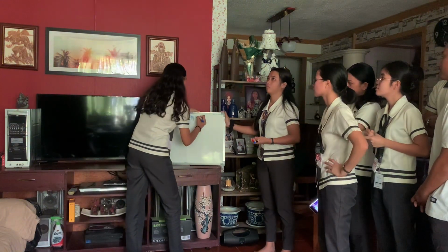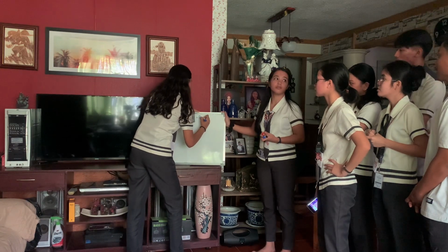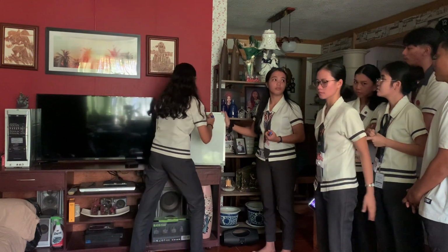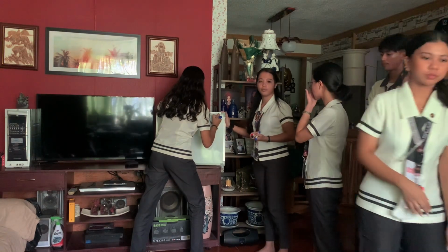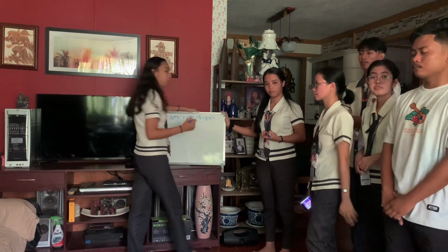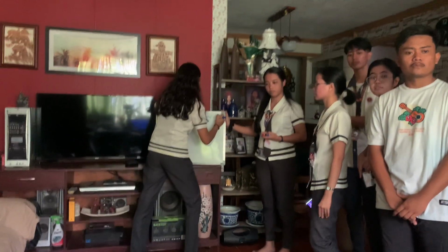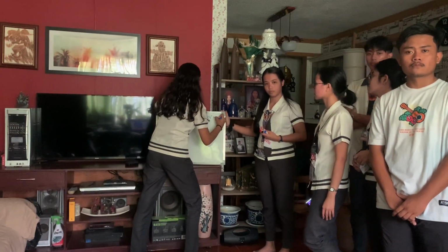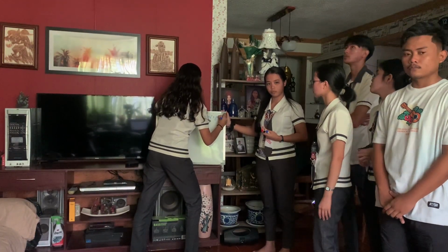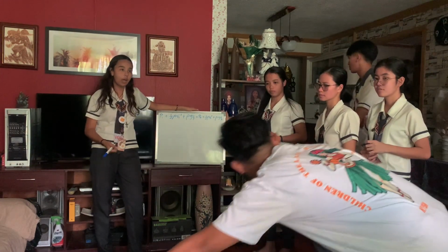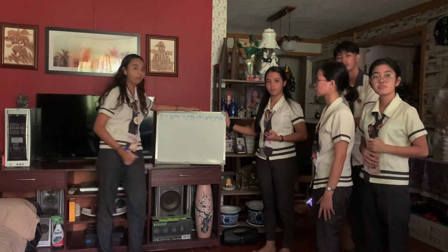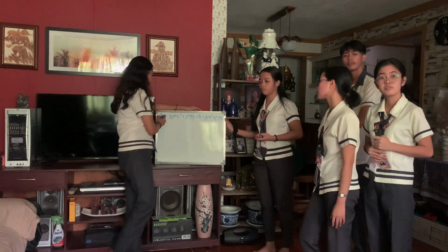The pressure at the hole is P2 plus its kinetic energy, 1/2 density times velocity 2 squared, plus its potential energy, rho g y2. Now, notice that I said earlier that both pressures have the same value because both are atmospheric pressure.